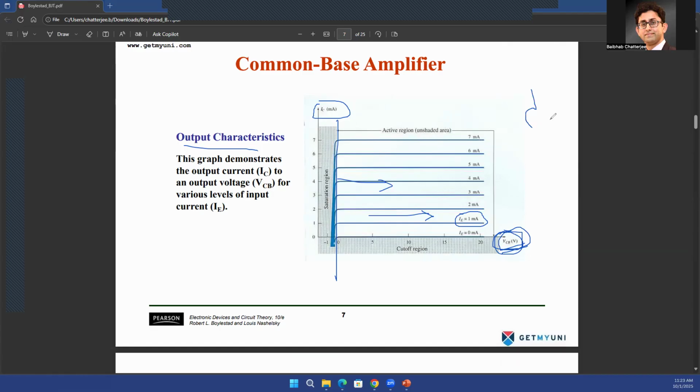So if you want to design a current source, what do you want out of it? You just want current. You just want a fixed amount of current, let's say 1 milliampere or 5 milliampere and so on. You don't want the current coming out of the current source to change depending on how much voltage is developed across it because of any circuit that you connect to it. That's our assumption, right? Whenever we see an ideal current source, we assume that the current is fixed.